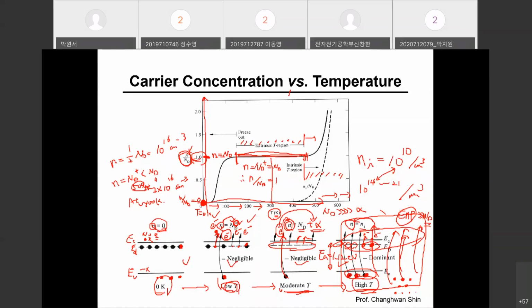More specifically, for your DRAM product and NAND flash product, or even if you use a DRAM module in your desktop PC. Maybe I'm expecting a very hot summer this year, because the winter was not very frozen, so your desktop will be exposed to slightly higher temperature if your air conditioner is down. Then the DRAM module would not be working very well. Why is that? The DRAM designer and process engineer have assumed that your desktop will be operating at room temperature. If your air conditioner is not working well, then your DRAM module will be exposed to a slightly higher temperature, so the total number of free electrons in the DRAM system would not be as expected. Therefore, some wrong operation would happen.